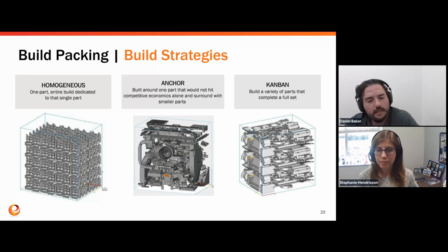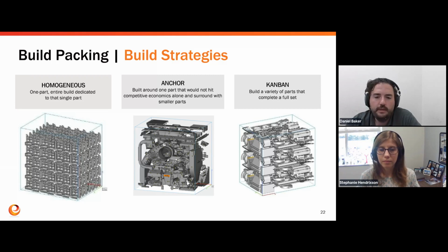I would say that's the most common thing we see: a customer knows that this is eventually going to be outside the scale of our production process, and they're going to want to make hundreds of thousands of these at a relatively low cost. So what we'll try to do is look at the total value of that additive life cycle for our customer, and say this makes sense to run up to about 1,000 units, and then you should probably cut a tool and go to injection molding, because that's where the two piece part price cost curves intersect, and it's going to be cheaper for you in the long run.